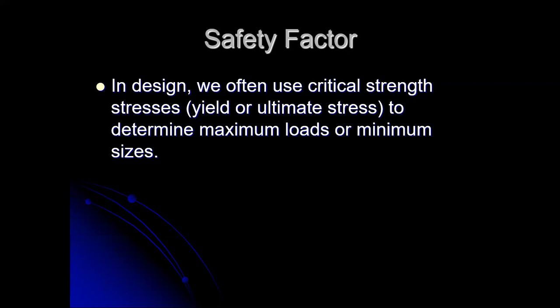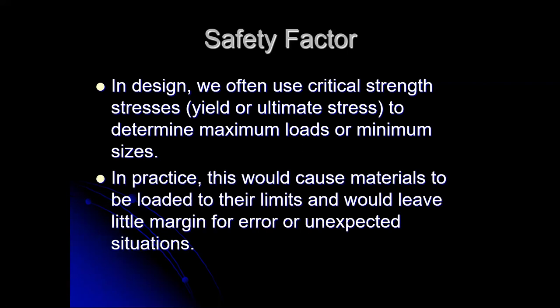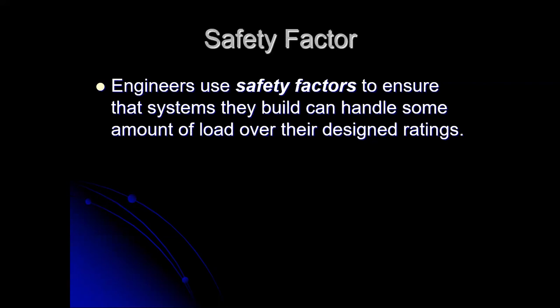We use those critical strength stresses, ultimate stress or yield stress. But in practice, we could leave very little margin for error or for unexpected situations. When we apply a safety factor, we are trying to ensure that the systems we build can handle some amount of load over their designed ratings.